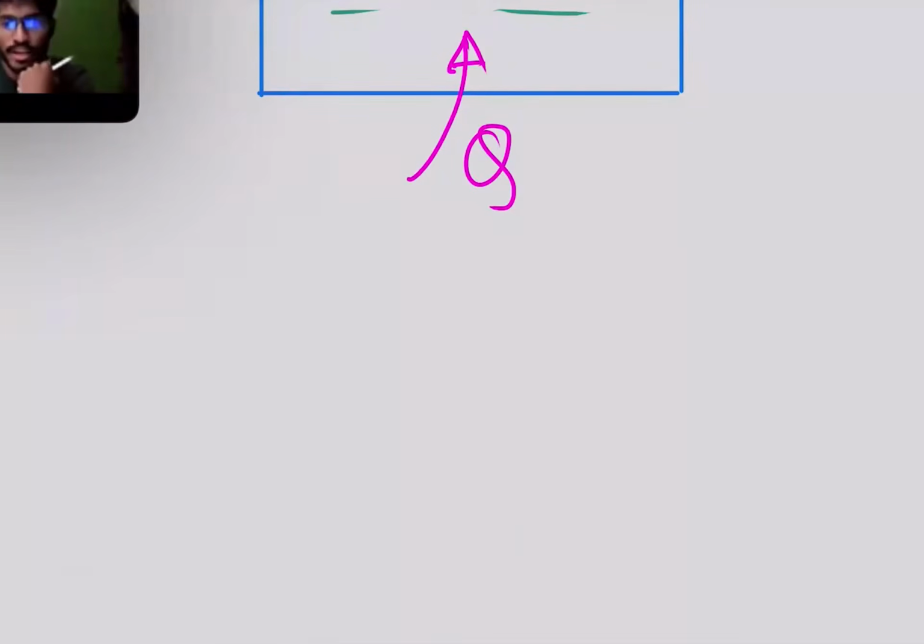And other than that, are the increasing lines, other than the flat line, straight lines? Yes, the two lines are straight, but their slopes are different. Why will the slopes be different? Because the specific heat of liquid and vapor are different.